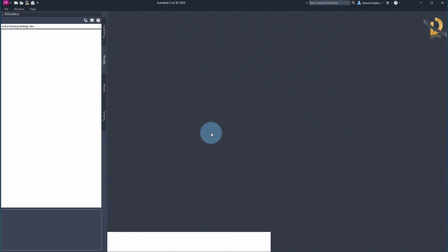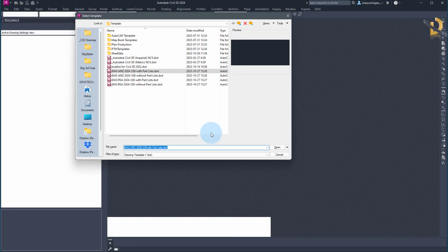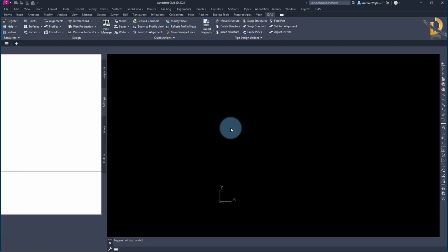In this video, I'll show you how to convert a polyline to a bulk water pipeline. First, I need to start a drawing on a correct template. So I will use IDA's ANZ 2024 version 338 with part list. Let me open that drawing.